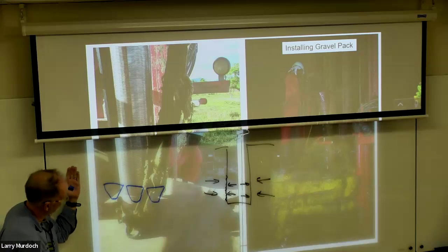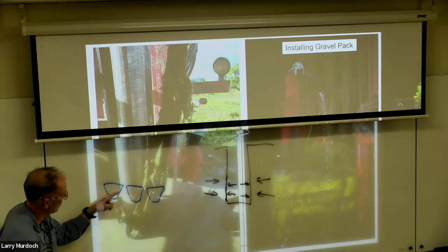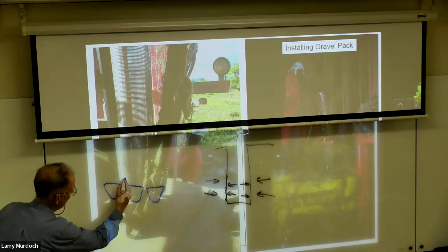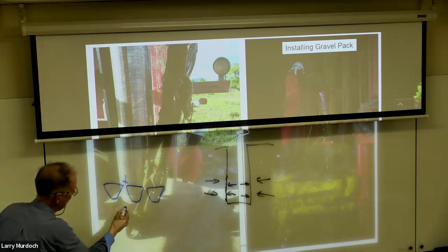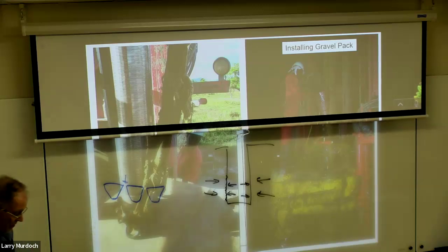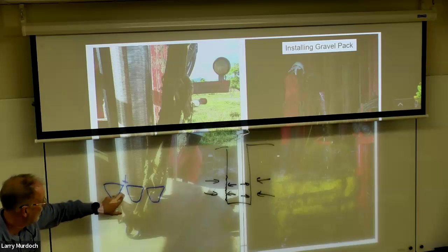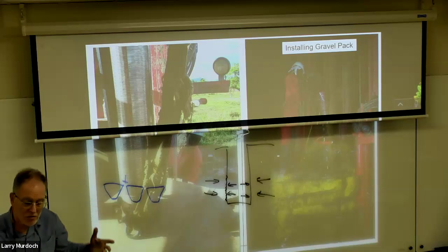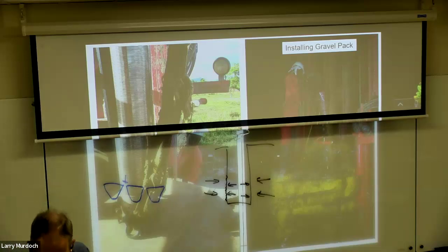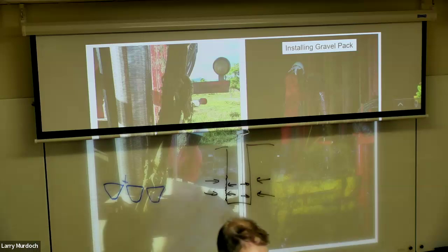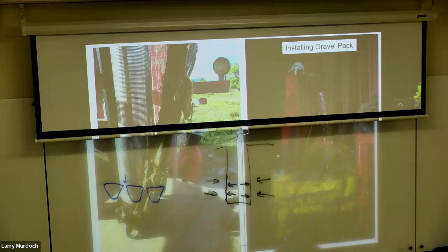So this wire is cut, and there's a very narrow gap right there, but it expands out. So it's a narrow gap to block the inflow of particles, but it expands out like this to reduce the head loss during flow. And then at each point where the wire touches the rib, it's welded.